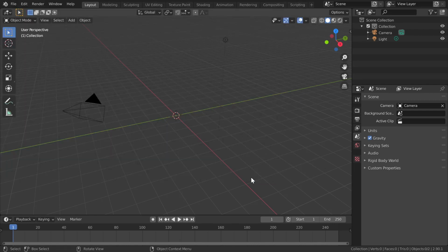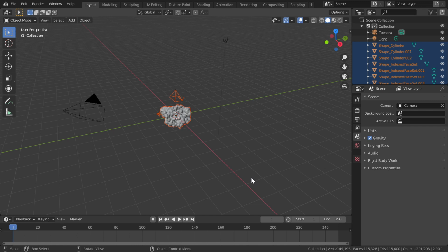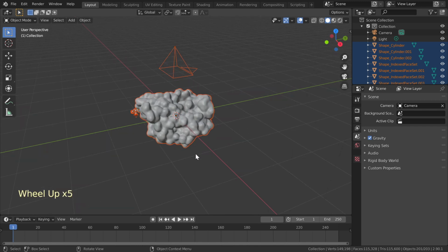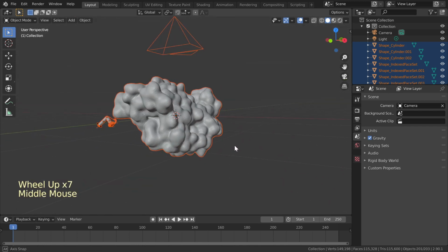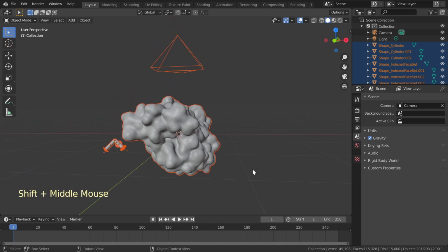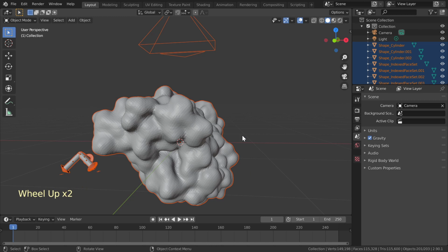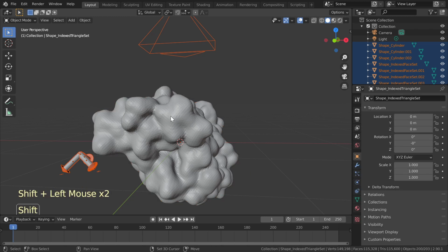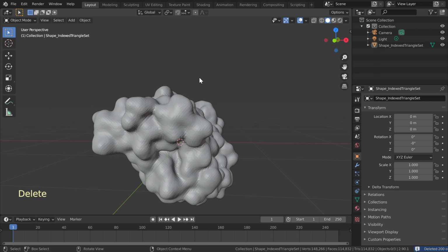Click Import. The imported object consists of a surface mesh, camera, and XYZ axis object. Note that you can prevent VMD exporting the axis object by hiding it before exporting. Press Shift and left-click the molecule surface 2 times so that it becomes unselected. Press Delete key to delete VMD's axis and camera objects.